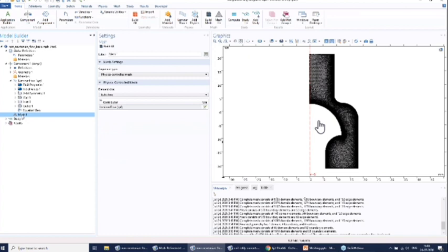Okay, so now what we will do is first mesh this problem. Once the flow happens here, at this bottleneck which you are seeing at the center, the velocity will be very high, and the gradients of the velocity will be high as well. So we need to capture those phenomena. We will see how many elements are enough to capture our physics accurately. This is the kind of mesh convergence study which we are going to do in this model.